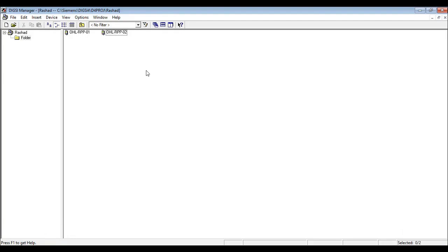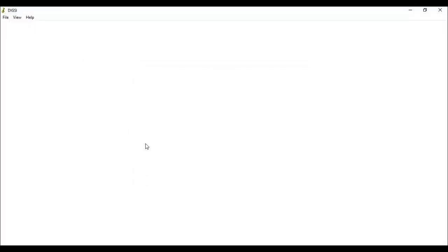So now I'm supposed to determine what the signals are that I need to exchange, or even the commands, between my relays and the SAS system. So how is this done? This is done through the masking input. First, I start by taking the first file I have and begin to open this file offline.